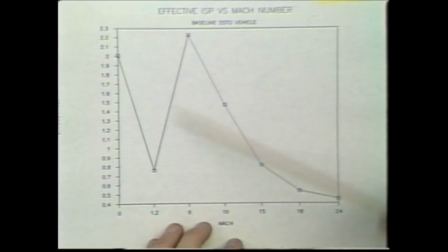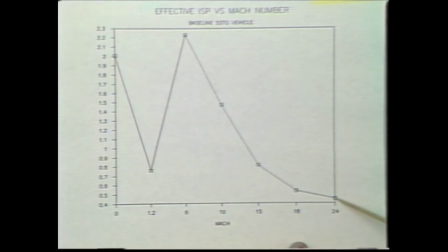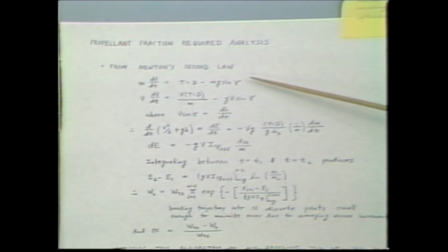But it's reasonable performance. And then at Mach 24 here, I just used a rocket level. By then, you're essentially out of the atmosphere, you've burned out, and you're operating on your rockets. Now, how much propellant did it require, given that level of performance, for our vehicle? Did we hit our 60% mark that we established its size by? Well, we can check that.